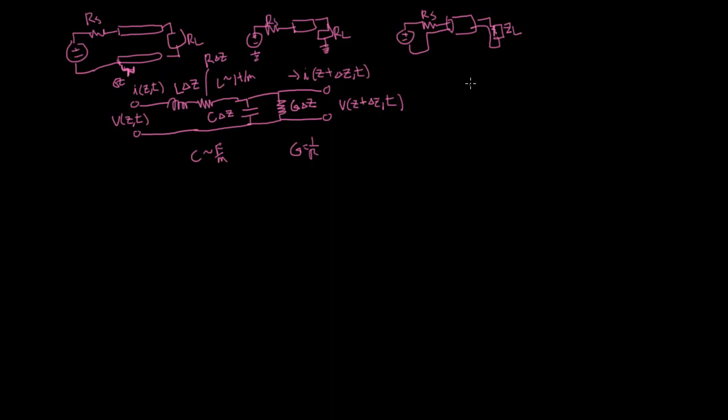So again, let's just summarize the units really quick. So L is in henries per meter. R is just resistance as we know it, but per unit length, ohm per meter. G is Siemens per meter, but this is also 1 over ohm meter. Just put that there in case since we don't really talk about things in terms of conductance as much. And C is just your usual run-of-the-mill capacitor, but also per unit length.